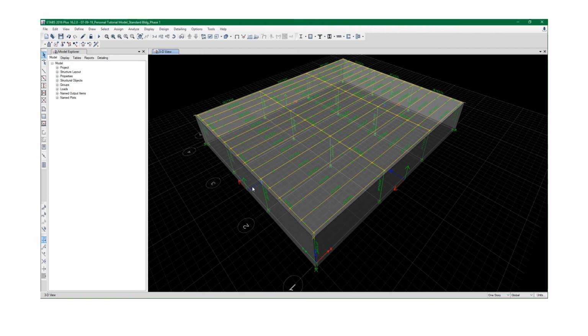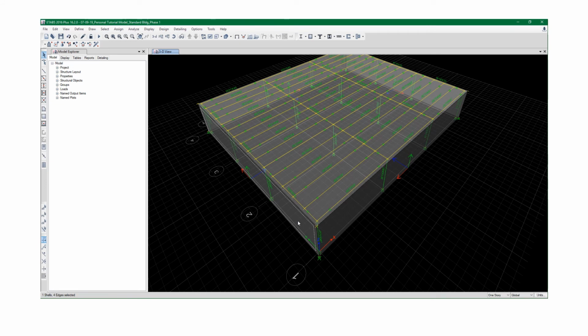So we want to put the windward pressure in the X direction, perpendicular to the windward wall, so it's pressing against it. Here my local Z-axis is going this way, parallel to our X-axis. So we want it to go in the same direction, and I'll use a positive value for my windward pressure.